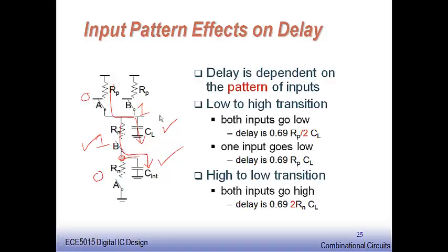Therefore, if we calculate the timing taken for the output to rise from 0 to the maximum, I will have additional time, what the current takes to charge even the CINT. Over and above the time needed for CL, I will have time for CINT also.